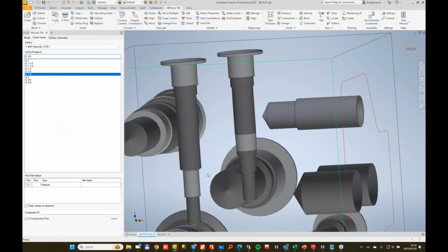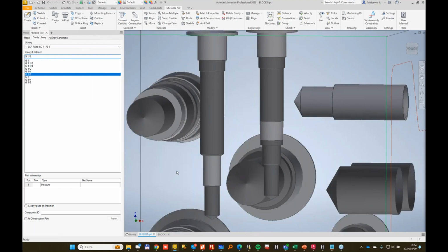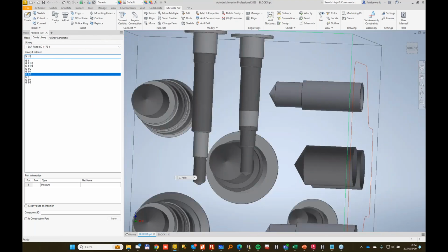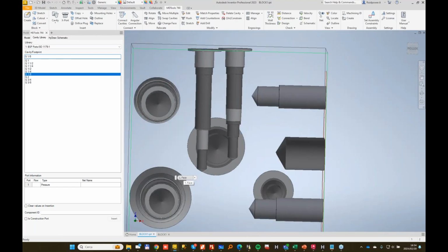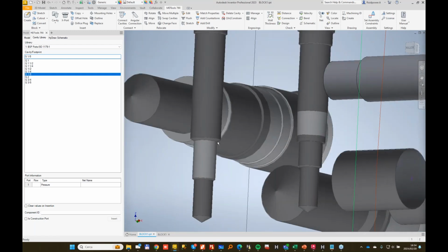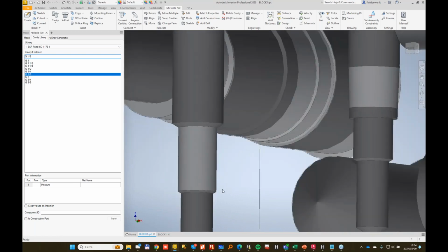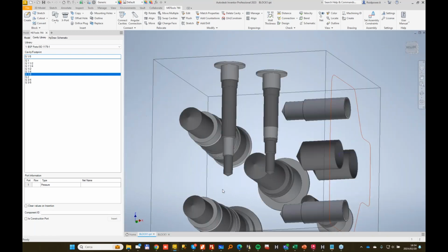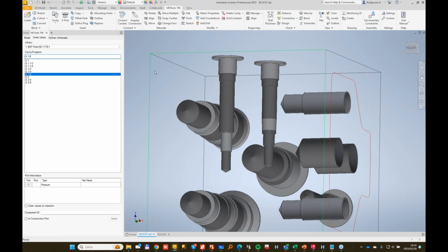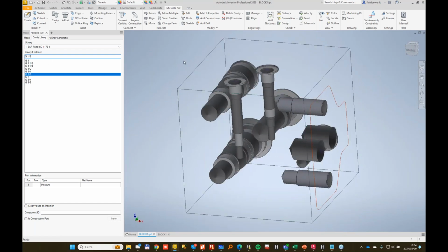And I think I'll use the same technique also for metric orifice plugs, because then I can really control the depth much more easily, because otherwise here the depth is calculated from the intersection between the cone and the starting point, and I really like to have as few decimal places as I want. So this is a technique for orifice plugs.